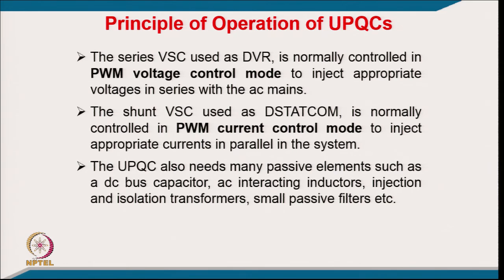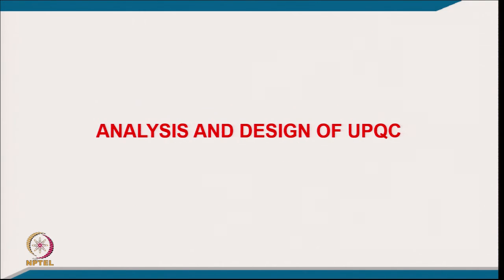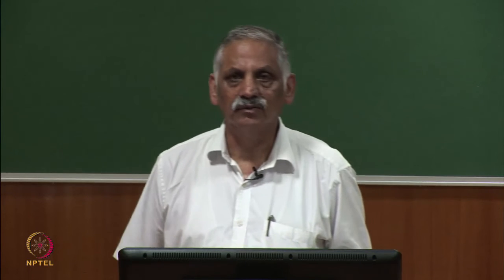So, certainly you need, typically, an AC inductor to interface this, and you require an injection transformer and isolation transformer, depending on series compensation or shunt compensation, and small passive filters, typically switching ripple filters. Coming to the analysis and design of the UPQC.